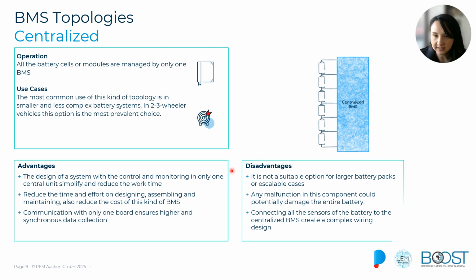All of the data of the battery pack will go to a single point where everything is being processed and everything is being analyzed. This simplifies all the diagnostics and the control logic that the BMS may have. And in addition, as we only have one single element to inspect, the maintenance and the troubleshooting are easier in this topology.